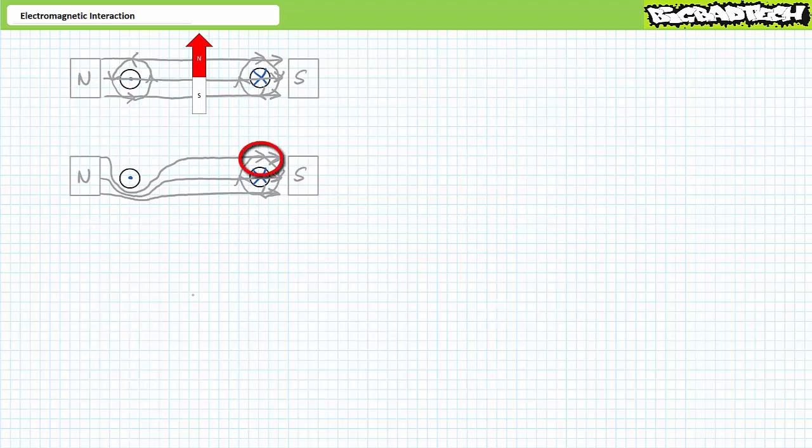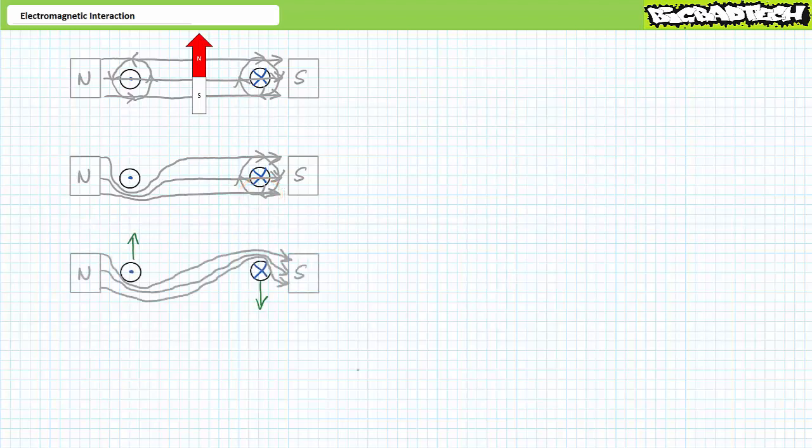Similarly, note the magnetic field on the top of the right-hand conductor is aiding, whereas the magnetic field on the bottom of the right-hand conductor is opposing. These fields coalesce so that there are fewer lines of magnetic force on the bottom and more on the top. The unified magnetic field on the top acts to push the right-hand conductor downwards. Given the left and right conductors are in fact cross-sections of the same three-dimensional coil, this coil will be torqued clockwise as the magnetic fields seek alignment.